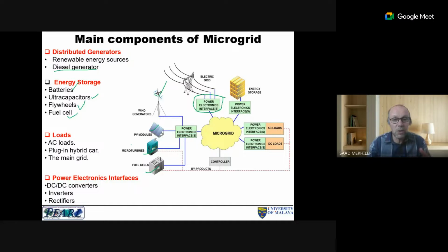That's why you can see the research in power electronics now moving from grid following to grid forming inverters. These grid forming inverters need to help stabilize the frequency of the grid, not just inject power. Before, it was only injecting active power, then reactive power, and now it has to help in stabilizing the grid.